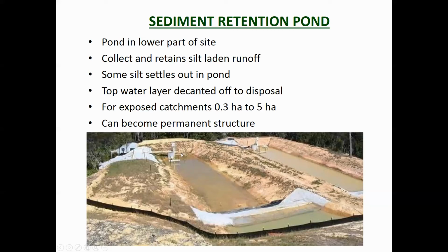Normally the proportions are 3 to 1. That is to encourage plug flow. If it was any thinner, it would be going too fast, and it would be resuspending the sediment that has settled on the bottom. If it was any wider, then you'd end up not being able to distribute the flow across the whole width of the wetland, and there'd be short circuiting. There'd be little channels forming. So we've found that a proportion of length of 3 to 1 wide is about right. This one's maybe a little bit narrow.